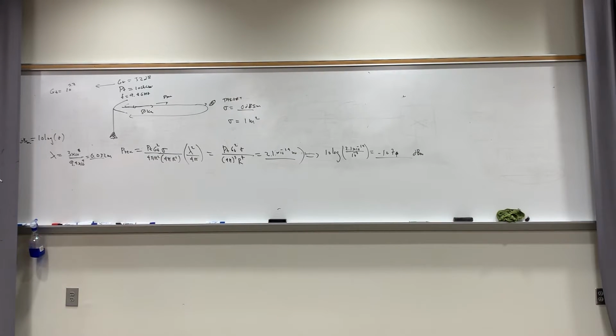And I don't know if your phones have that. I'm sure they do. Have you ever looked at this? You used to go into a special code inside of it that you can get to. Which is interesting, about minus 100 dBm is kind of common for the power levels. You get from minus 80 to minus 100 all the time, which is kind of amazing. Your phone can extract data from that signal. And there's a couple ways they do it.